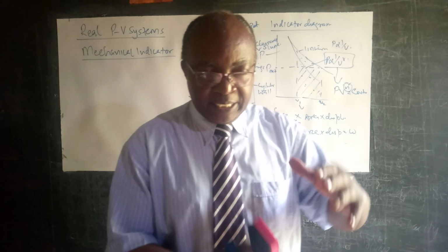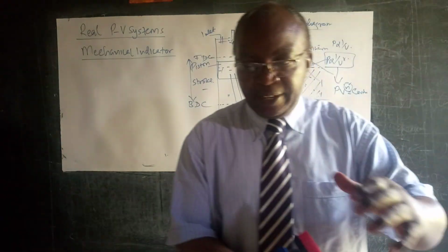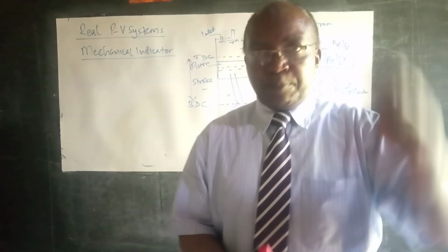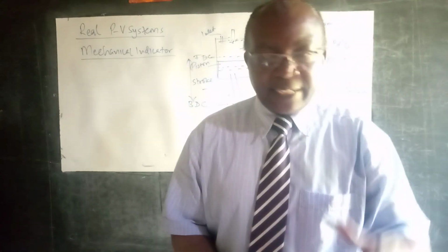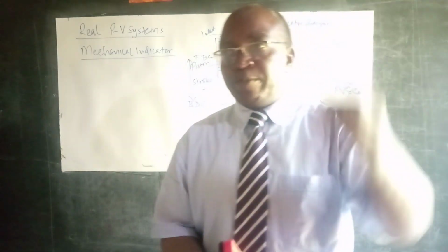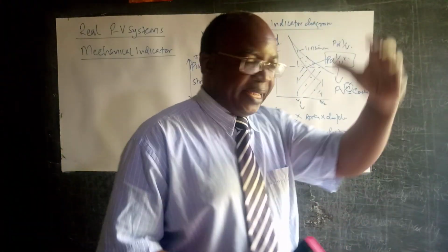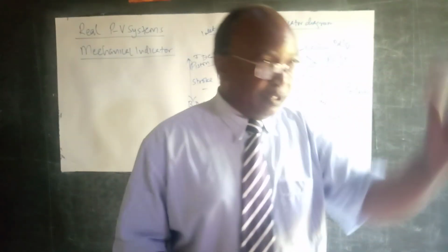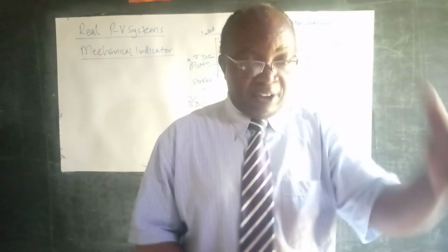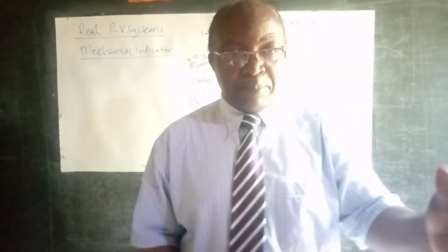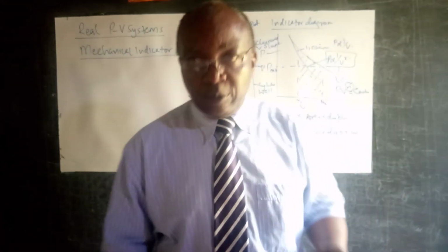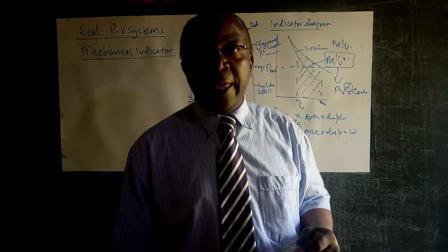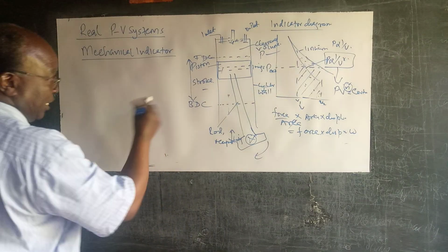This piston itself is attached to a spring that ensures that the movement of the stylus, which will be drawing the profile on the chart in the drum, is proportional to the pressure. Let's just have a schematic of it.